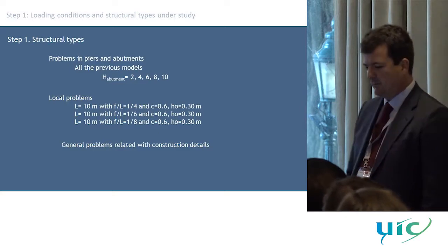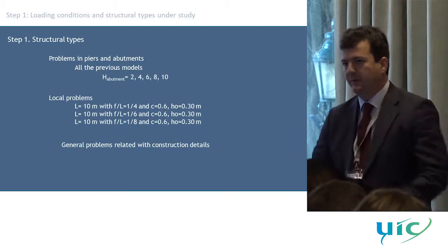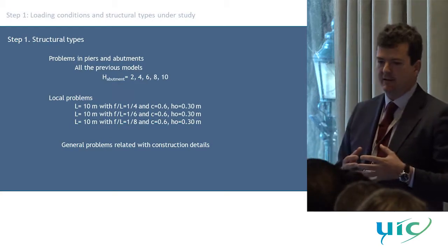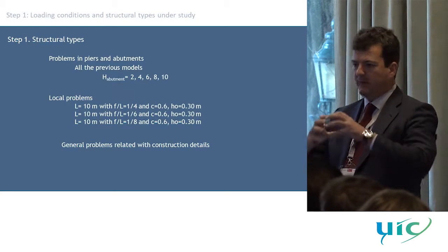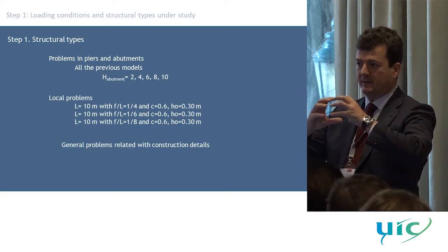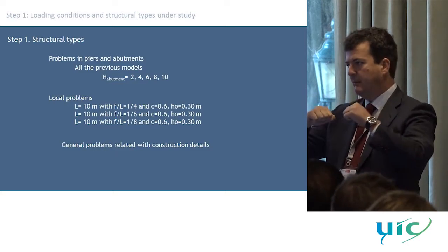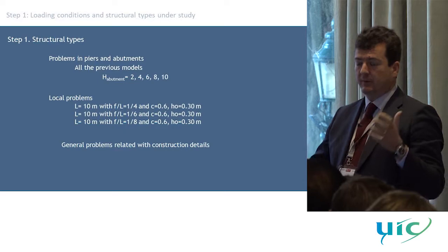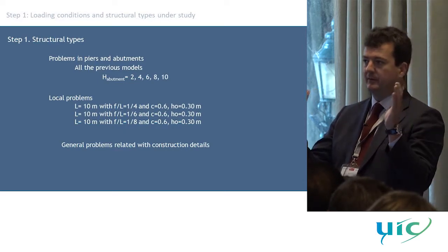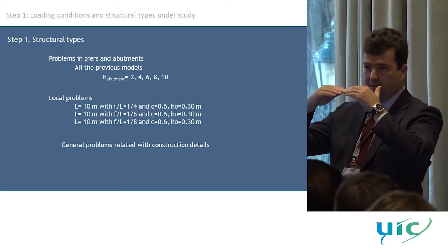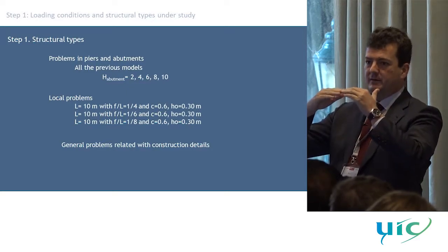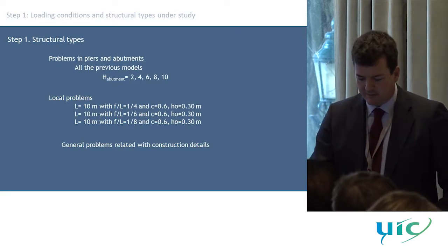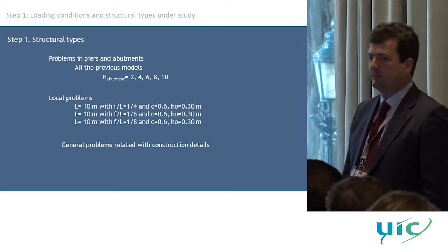Also, we thought we could have some problems with stresses locally, but we also thought that the real problem is that when you increase the live loads, maybe the barrel can support the new thrust, but it is going to give a huge horizontal action to the abutments. If the abutment is not well supported by the passive pressure, it is going to overturn, and if you have the overturning, you have a 3-hinge mechanism in the vault, and you have this every time a train passes over the bridge, many times a day. And this is related again with fatigue problems and the serviceability limit state.